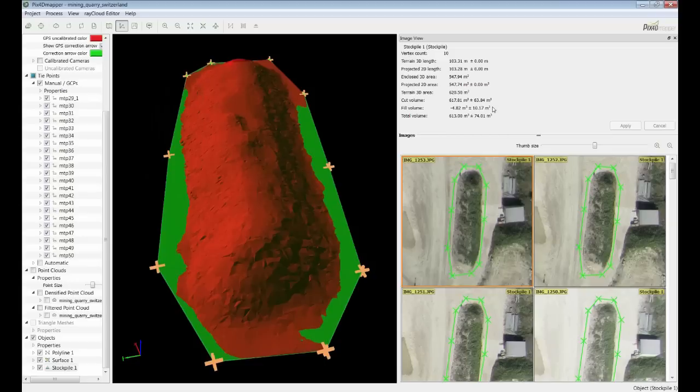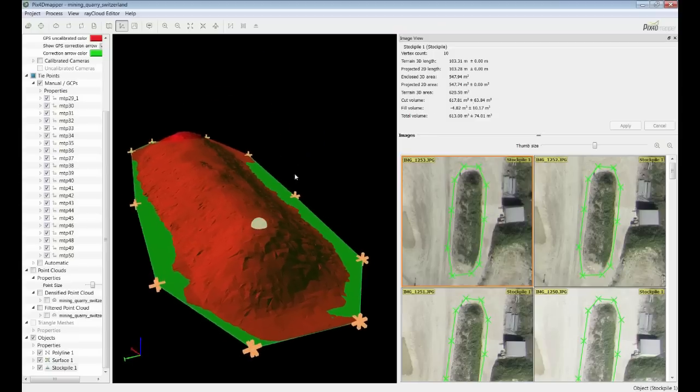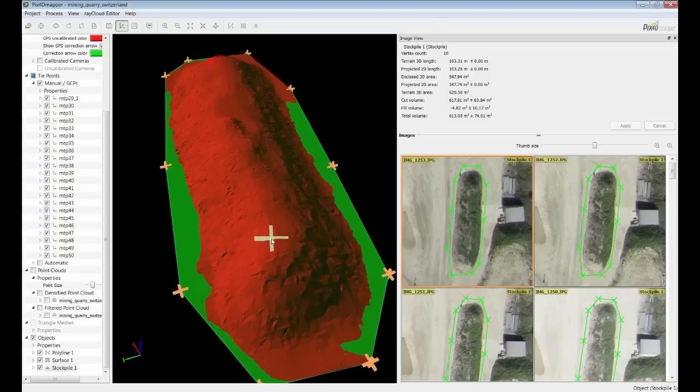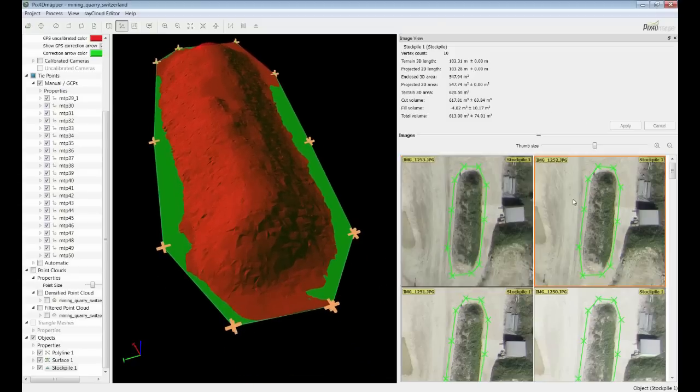In the case of volumes, we also do measurements of inaccuracy, and these measurements will depend on the ground sampling distance as well as the size and characteristics of the volume you're trying to assess. To get better volume estimation, the main recommendation is to use a dataset with a higher resolution, meaning a smaller ground sampling distance.